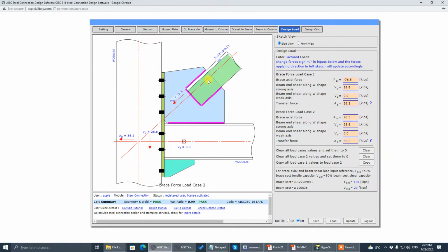The design check for the brace is different, because you have buckling for compression, and you have tensile breakout for the tensile case. So they are different, don't think they are the same. The shear force pretty much will be the same for both scenarios, and we have V-axis shear too.